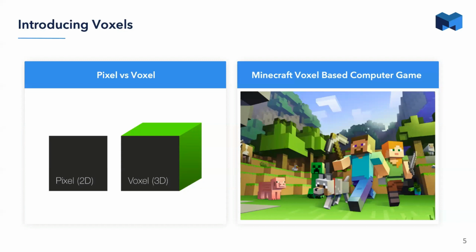The other area is a form of mapping called VOGs, or voxel occupancy grids. And these are typically used in robotics for small robots that go into a room, it has a LiDAR sensor, and it builds out a 3D map of the environment that it can localize itself from. And this becomes a small dynamic map, which it stores for a temporary amount of time and then deletes as it goes into different environments.